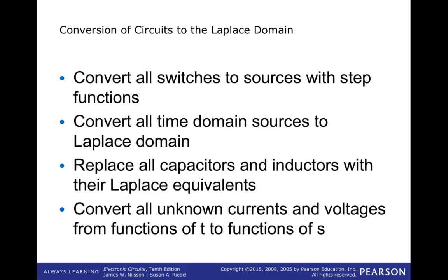The second thing you want to do is convert all the time domain sources to the Laplace domain. So once you've gotten rid of those switches and replaced them with step functions, then you convert all the time domain sources to the Laplace domain. In Laplace analysis, the sources do not have to be DC. They actually can be any function, because basically you're just going to take the Laplace transform of the time domain function of the source, and that will represent a Laplace domain function of the source.